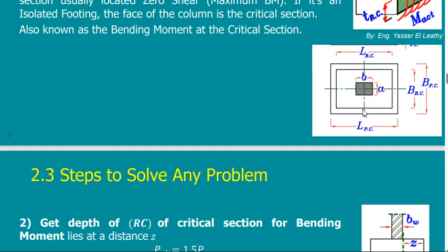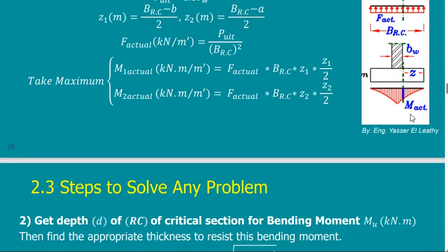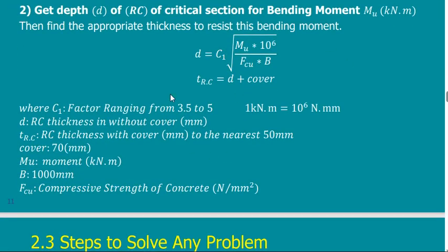So it is just one case for design. If you do not do this, it is not wrong, but it will be more expensive, because the cantilever will be longer from one side than the other, so the moment will be increased. That's all. This is how you calculate the moment, and so on.